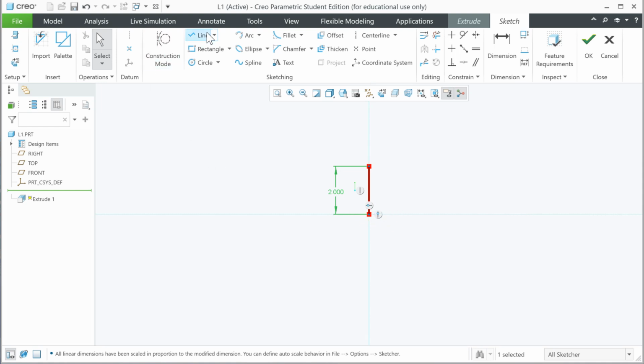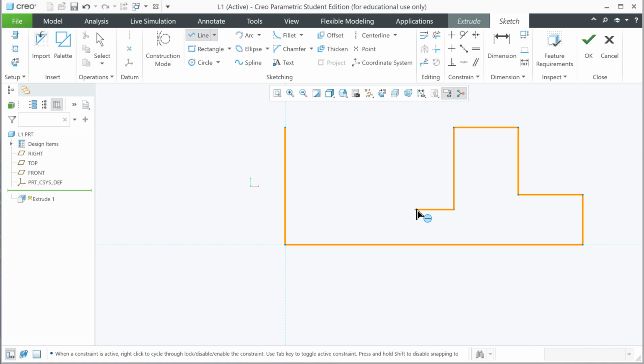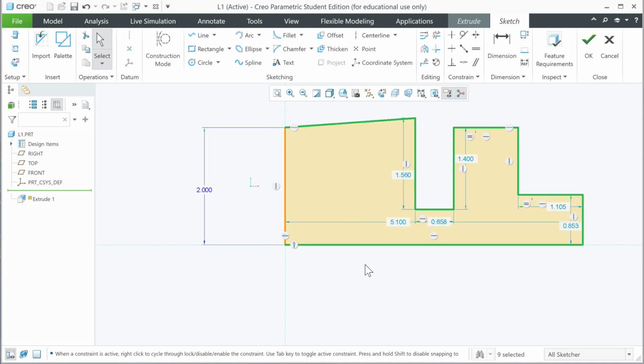Now, I'm going to go to the line tool and construct the rest of this. So I'm going to drag this across. It kind of looks like this. And what's neat is you can conceptualize this. Go about the same height here. And then across. Stay away from equal. See that little equal symbol to the right? That's not always a good thing. So stay away from equals. Even though there is an option in the tools options, you can turn that off. So just make sure there's no equal symbol to the right of your pointer. Drag this up. Oops, and double middle click to end the chain.